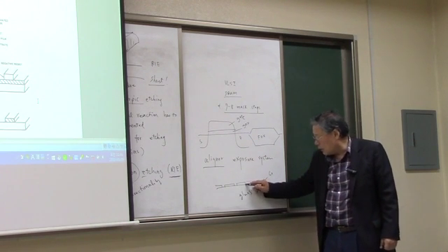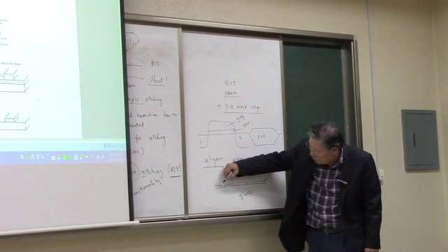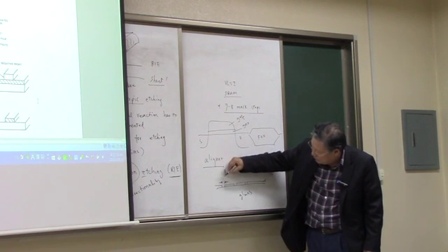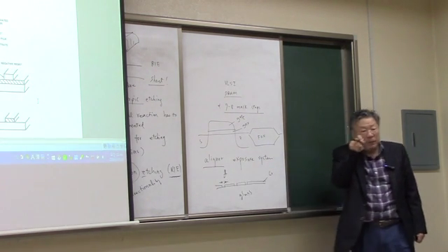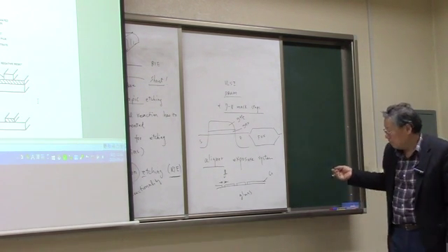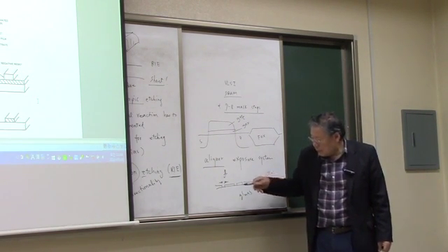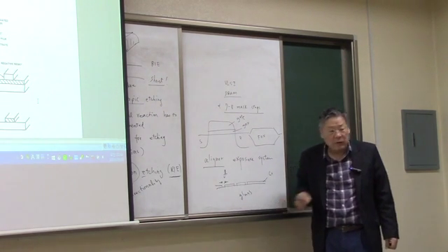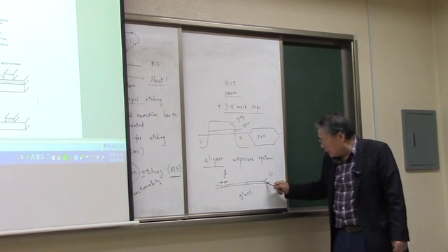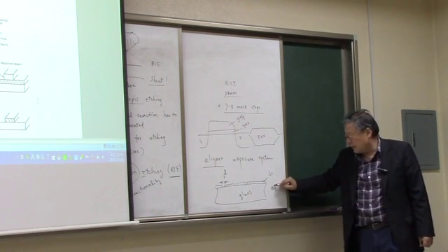Okay, so you use the laser just to melt down the chromium, and the resolution here is less than 1 micron, of course, because the laser beam can be focused less than 50 angstrom or something. Okay. So you can create very sharp lines with a high resolution. And then with this glass, we call this mask, okay?